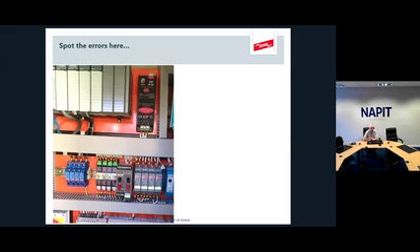And the other thing was, this is at a remote location, and although the SPD has the facility to give feedback remotely, it wasn't wired up. One of those blue plugs on that blue SPD on the right hand side there had failed and nobody knew about it. So there was no protection in the installation whatsoever. So what we're looking at is that the location of the SPD has got to be with as short cables as possible, and you've got to locate it at the zonal interface there.